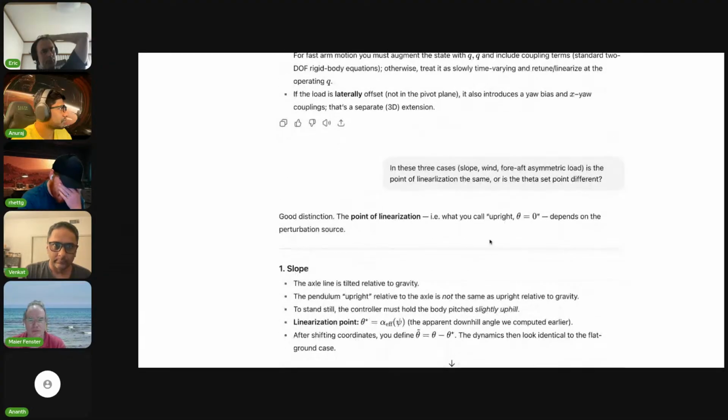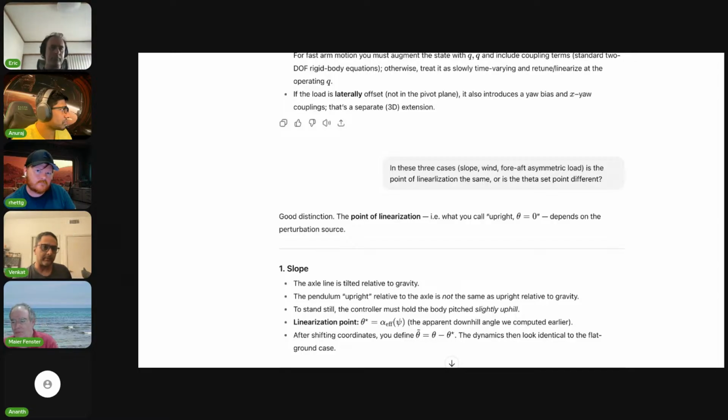So does that imply that the same model, the same control system that you would build to work without that, wouldn't work with it? You will still have to accommodate it. The same structural model will work, but you might have to substitute the parameters with some effective loading. Instead of the literal length of the pendulum, you might have to compute the new center of mass and put the virtual line connecting it, things like that. So there's some control strategies for that stuff, but the basic dynamics don't change that much.